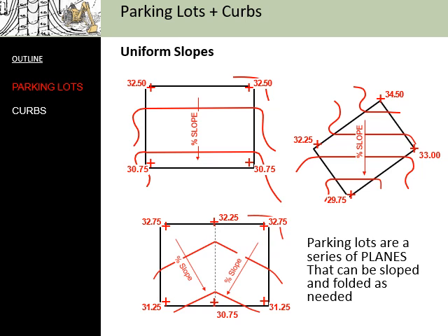We want to do that in part to cut down on the cut and fill, and we also want to do that to preserve existing vegetation. And of course, we want to be thinking about the drainage and how we can direct the water either to inlets or more commonly to bioswales where the water could be filtered and recharged. And that focus on drainage is something we're going to come back to again and again.